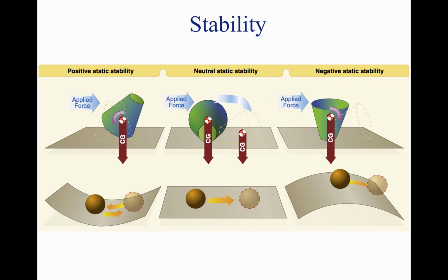Each aircraft responds to control inputs differently and therefore handles differently. For example, a smaller aircraft might respond rapidly to control inputs, while a large transport aircraft may feel sluggish and slow to respond to inputs. These features can be designed into an aircraft to facilitate the particular purpose of the aircraft by considering certain stability and maneuvering requirements. There are 2 types of stability: static and dynamic.